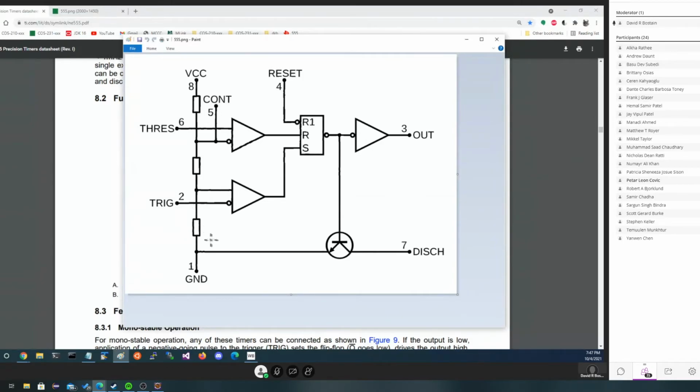Let's assume for a second, and I'm going to use a number we wouldn't really use, but it just makes it simpler to look at, that we have 0 volts right here. And let's assume for a second that VCC is 6 volts. That means that if these resistors are equal, I will see 1/3 of VCC right here at that spot. And I'll see 2/3 of VCC right here. So the voltage at this spot right here, if this is 0 and that's 6, would be 2 volts. So it'd be 2 volts right there, and there'd be 4 volts right here.